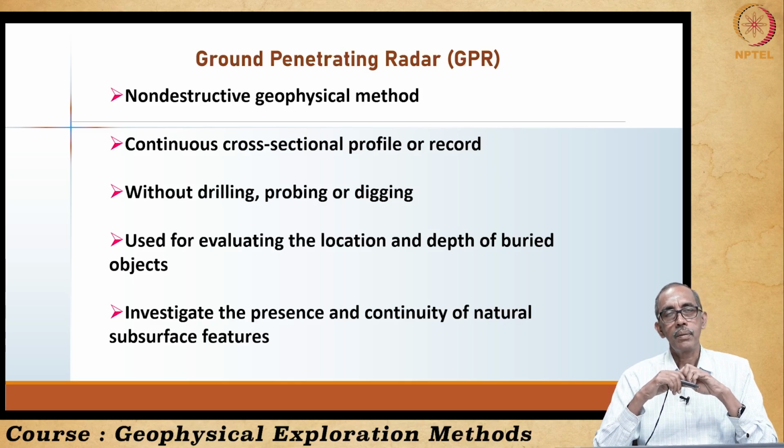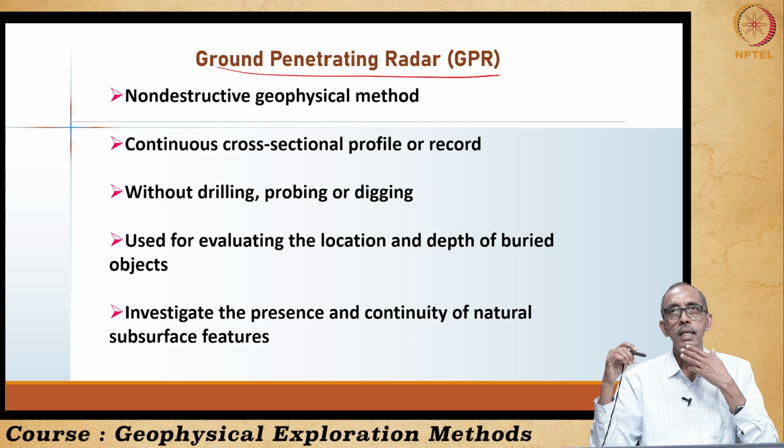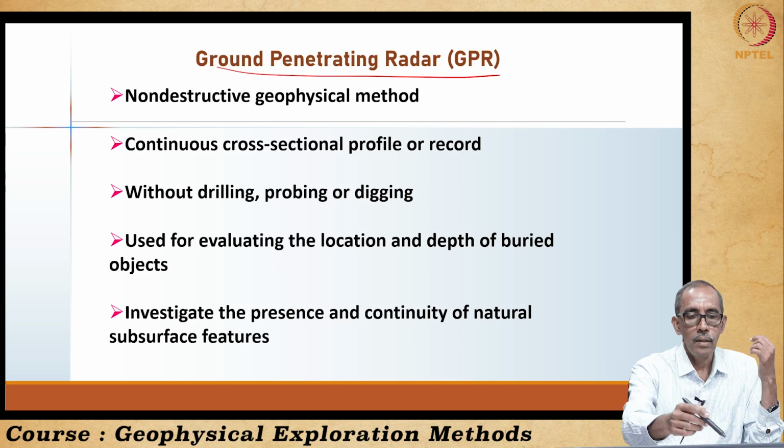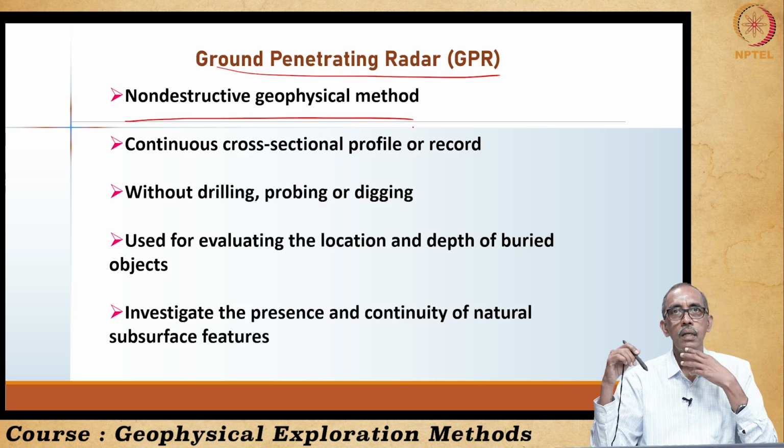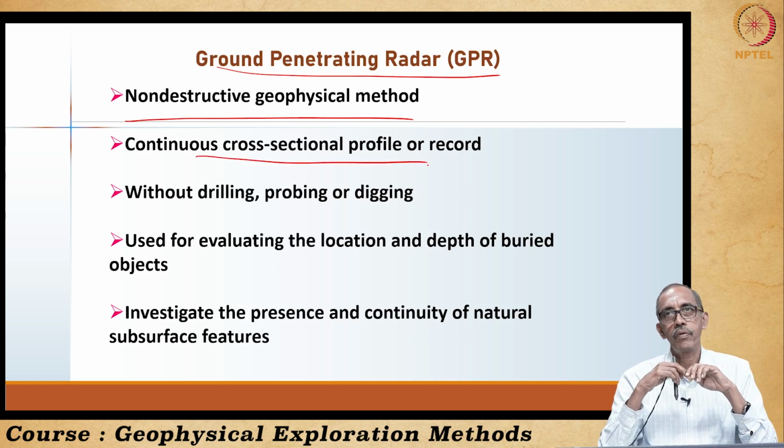The next subsurface investigation method is known as the ground penetrating radar method, popularly known as the GPR method. This is again one of the easy methods, known as a non-destructive geophysical method. The advantage is similar to the electromagnetic method. Here we can also get a continuous cross-sectional profile, right.